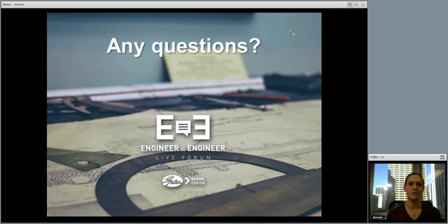Great, and our final question so far is which product line should I use if I am concerned with energy efficiency? So in general, synchronous is going to be a great option because it's about 5% more efficient than V-belts. So our two premier lines in that are Polychain and Power Grip, so either of those would be great options.